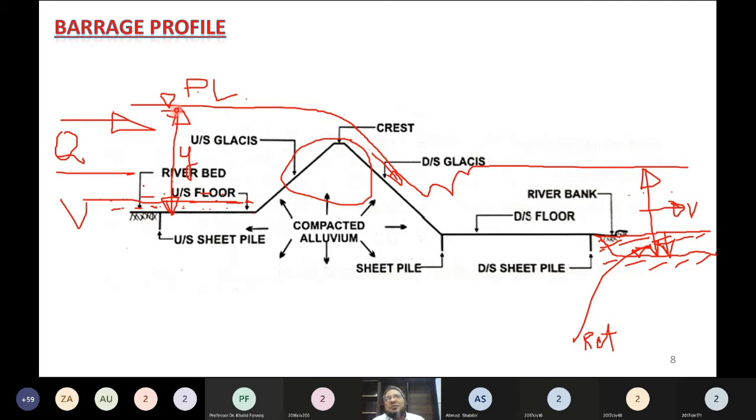No, the depth of flow on the upstream you increased, you disturbed the river regime. The river was flowing earlier, and its depth was perhaps this much. On this value of the discharge, this was the depth of the river. You made this structure in the river. You disturbed its normal flow. And what happened? The depth of flow on the upstream side increased. Due to that, sedimentation is a must on the upstream side. So as less silt-laden water is moving on the downstream side, it has to pick up silt from the downstream side. So the accretion cannot take place earlier. Okay, sir. Okay?